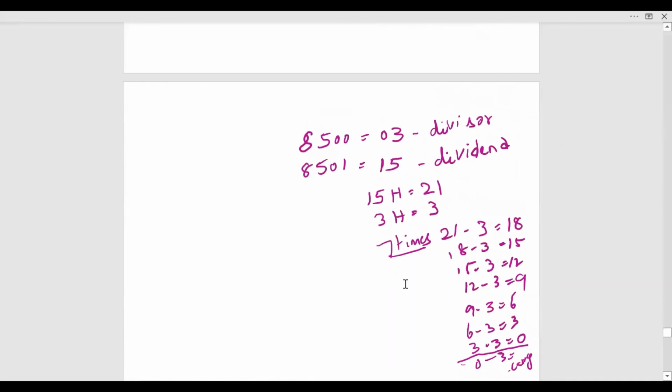Division is nothing but repeated subtraction, because 8085 does not contain any instruction for multiplication and division. So for multiplication, we have to use the repeated addition process. Similarly, for division, we have to use the repeated subtraction process. So take the divisor in 8500, dividend in 8501, and then 8502 contains the remainder, and 8503 contains the quotient.